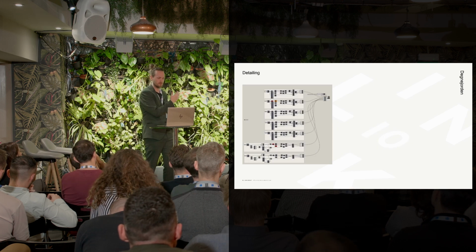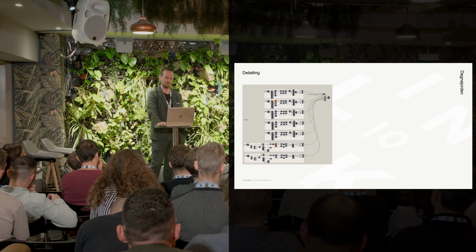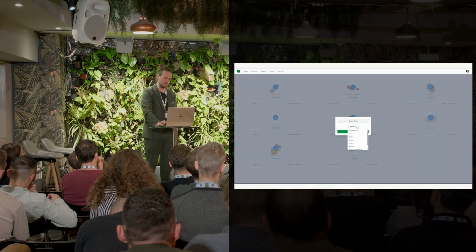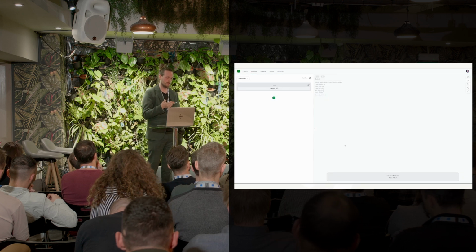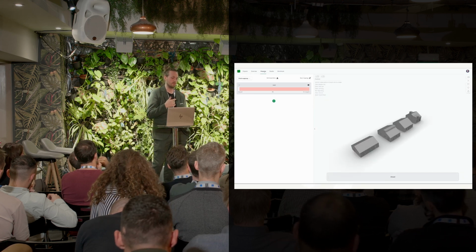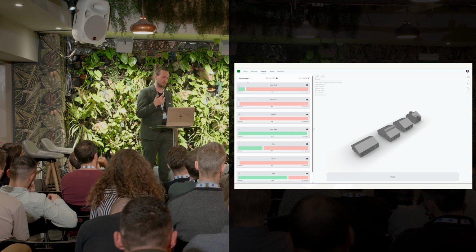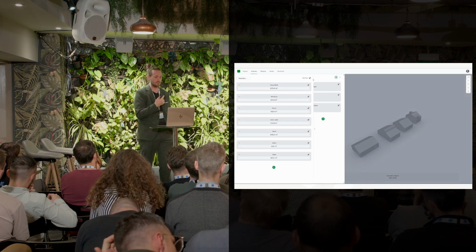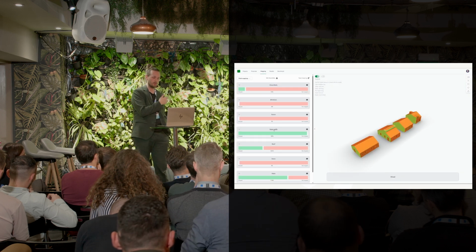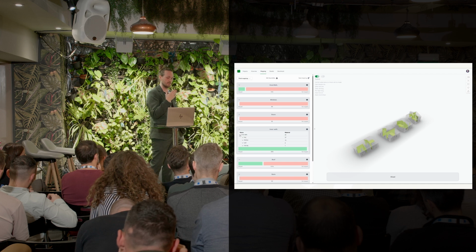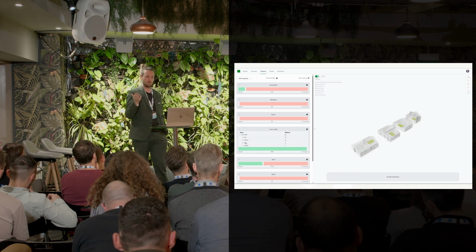So the script adds a few categories, and since we've done the mapping once inside of the application, we can load this, and when we have a look at the project, we can see our phase 1 mapping that we already made. We get automatic mappings from it. It's going to filter based on how you did before. And you can see that interior walls are the same. You already have them mapped.